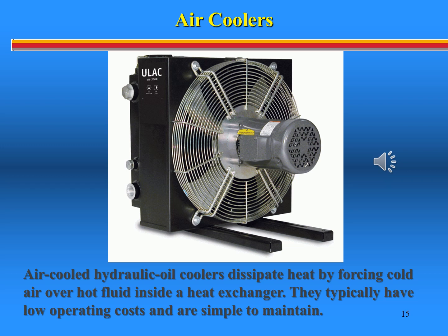On the downside, the upfront expense of an air-cooled system exceeds that of a water-cooled unit. Air-based versions are also larger and generate more noise, so they can degrade the work environment. What's more, these coolers require ventilation and clean air, and variations in ambient temperature can greatly affect cooling capacity, making steady-state operation more difficult to maintain.